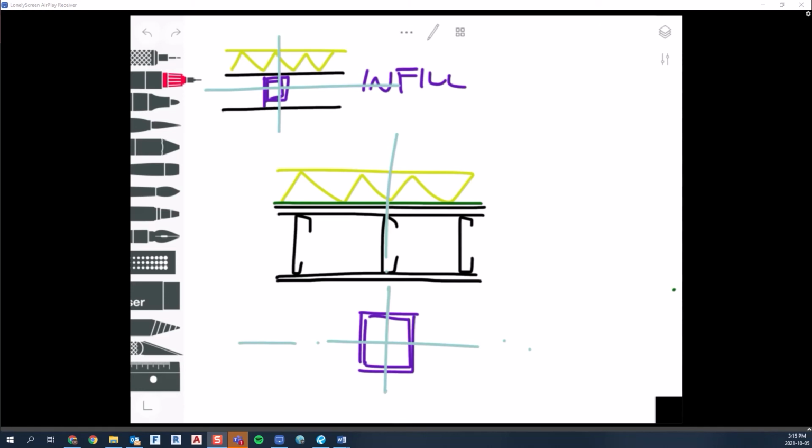The other benefit of this is, if we go back to the infill situation, there was quite a bit of coordination there, dealing with the base plate, making sure the engineer buries that base plate or makes it rectangular so it fits in the stud wall, coordinating with the structural engineer, making sure that the column fits within that stud space.